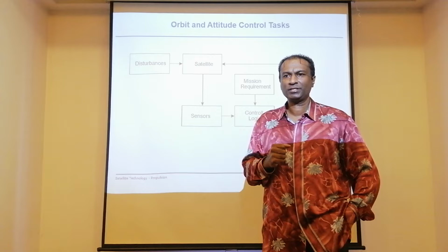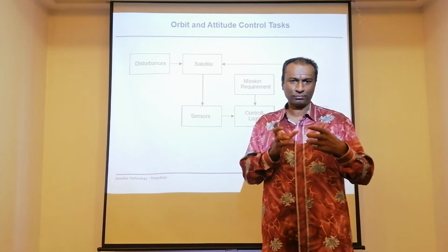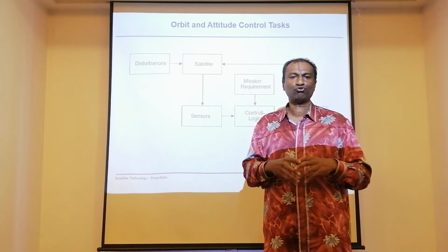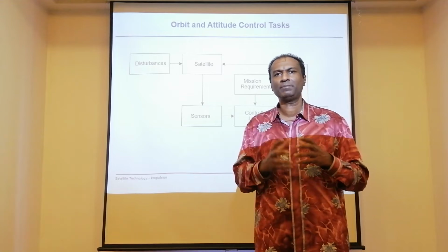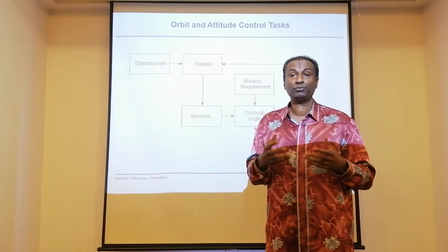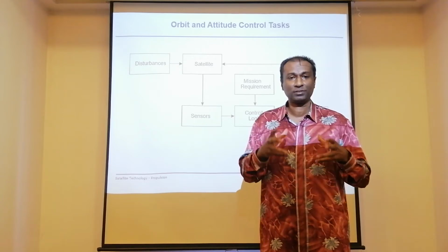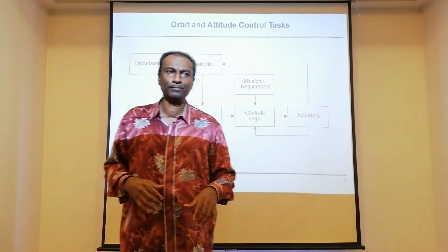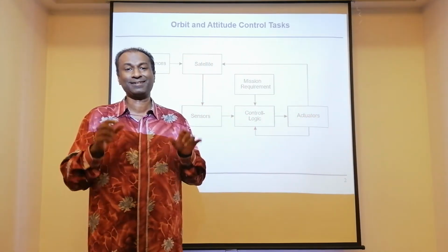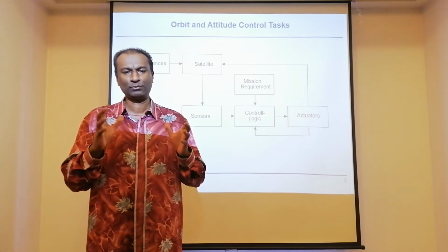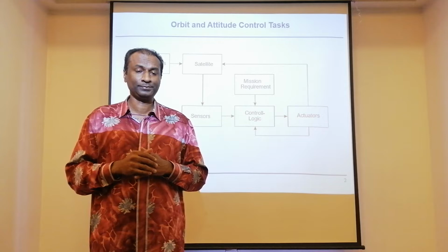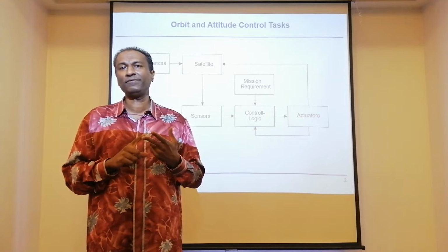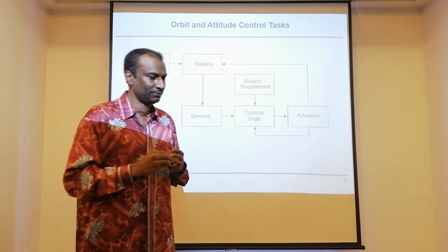So these are the two motions that we always have to talk about when you want to fly a satellite. Now, in chapter 3, we treated the rotational motion with devices such as the reaction wheel, momentum wheel, control moment gyro, even the spin stabilized technique. That is going to provide us with the rotational motion. But there is a system, for example the propulsion system, where, depending on the way we mount the propulsion system, or the thrusters, in our satellite, it can give us either rotational motion or translational motion, or it can give us both motions. So that is important to understand.